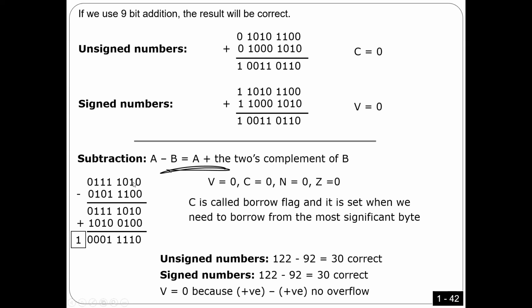Some students told me you always do addition. What about subtraction? So subtraction is addition. As I said before, it's addition, but you add the two's complement. So for example, I want to subtract this number from this number. Is that good, guys? So what I did is addition. I'm going to add this number to the two's complement of this number. Tomorrow I'm going to give you addition. That's fine. But I just want you to understand subtraction is addition.